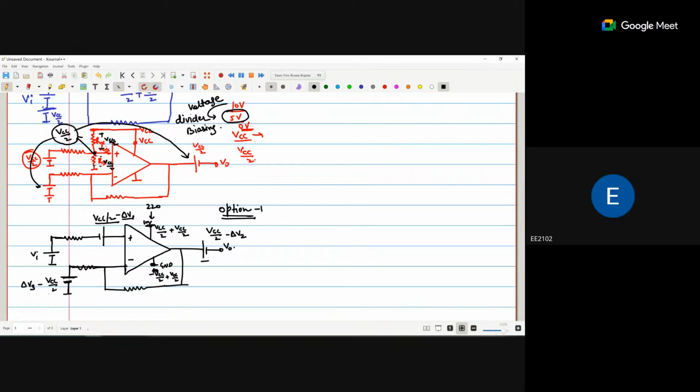One battery may be new, so it will discharge slowly. One battery will be old, that will discharge fast. So it is possible that the discharging voltage of different batteries will be different. And if the discharging level is different, you are getting a different voltage. So your output will never be a correct output.